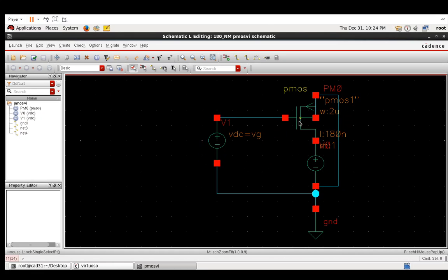And the same thing here, because this terminal is connected to source. See the connection here. Okay, see, it's connected to source through this wire. So whatever is coming here, if I keep making it come as negative values, then automatically VGS will become negative values. So that way we can make sure that we are giving only negative values for both VGS and VDS. So once we know that, then the rest is the same.